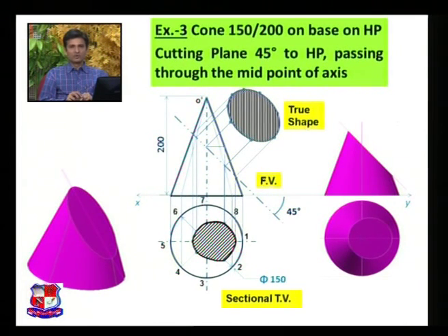Name the respective views, say front view, true shape and sectional top view, and also write down the scale which is used to draw this drawing. If you have used the scale 1/2 or 1/4, the appropriate scale should be written below this figure anywhere.